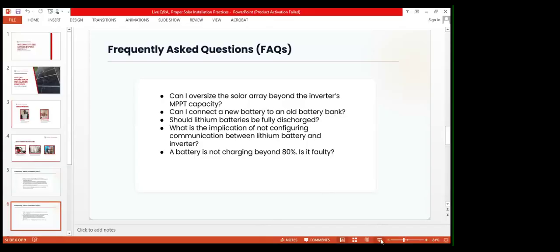So if the new one is now taking 20 amps, and the set value before was 20 amps because we were using one, when you want to set the charging current now, because you are paralleling another battery that is supposed to take 20 amps with the old one that was taking 20 amps, but because it's old, when you bring the two together, you cannot adjust your charging current to 40 amps because they are two in parallel. You want to double the current? No. If you do, it is the new one that will be charged with that 40 amps and it will get damaged.